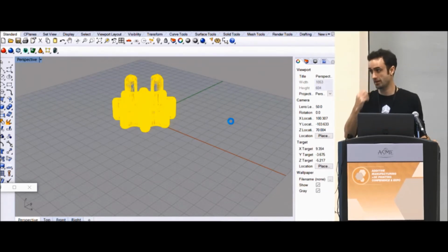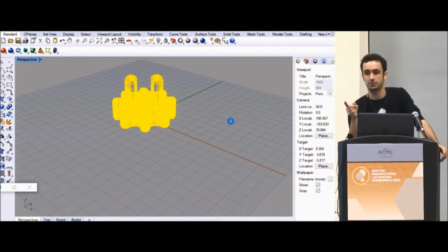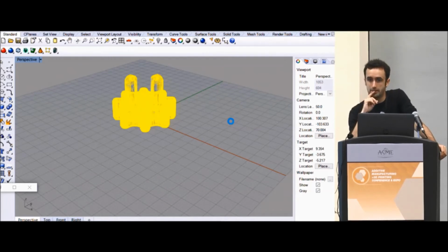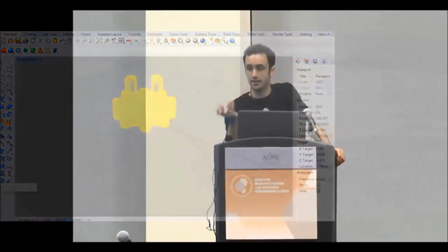Yes. So normally, for design and assembly, I'll design parts that are printed as one assembly. I don't even put them together. They come out of the printer fully assembled. And so a lot of times it's basically just tolerancing and making sure your parts don't fuse. On the specific SLS machine in my office, from some experimentation, we figured out that parts fuse at under 0.4 millimeters. So if I have anything less than 400 microns, they'll probably stick together. I should probably print them separately and stick them together if I want tighter tolerances.